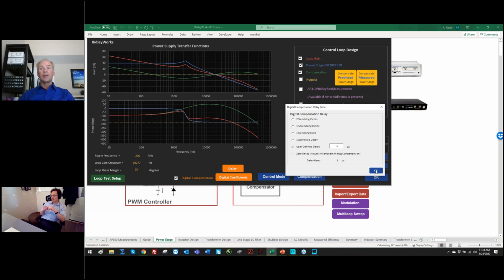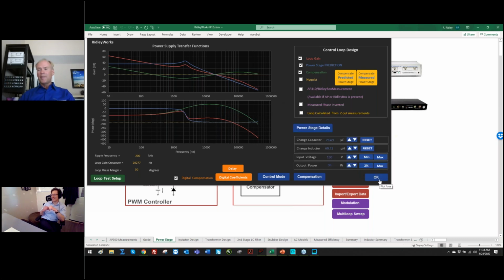We leave that to you, quite honestly. At the end of the day, you have a little control card. You've got a little tiny chip on it, and you put analog in, and you get a duty cycle out. I don't care if it's got comparators in it or whether it's got code in it. The power stage design doesn't change, and that's mostly what we do.